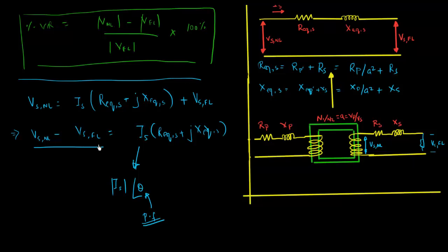What happens is, when the transformer, for example, is lightly loaded, you would have a voltage rise, and when you increase the load, your voltages will come down. Now this difference between light load and heavy load durations needs to be controlled and needs to be minimal. That's why when you buy a transformer, the manufacturer gives you different voltage regulation values at different power factors in the test data.